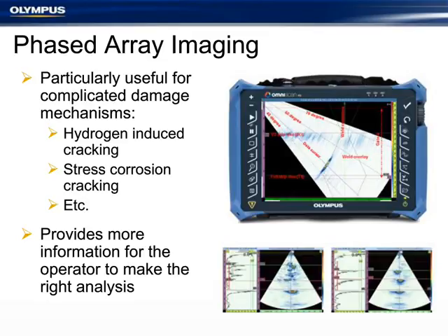Here we have shown a typical S-scan or sector scan image of a phased array of a weld. We have a weld overlay that we can actually design in the actual weld profile, which is a huge benefit in positioning and correctly characterizing the flaw. We have centerline markers. We have leg skips where we can actually see the top and bottom of the component. And then as we can see here, when we see a flaw, it lines up correctly based on its positioning to the sensor. So really what we're doing here is giving 35 to 40 times more information than that single A scan and putting it together in a representative way, so the operator doesn't have to try to understand many different single bits of information. It's a very powerful tool.